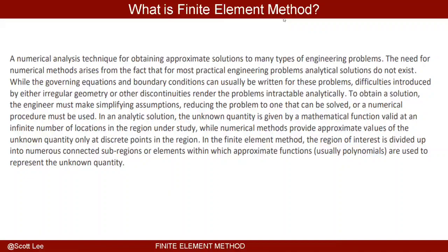Well, what you do is you simplify that domain into simple shapes like squares and triangles, and you want those triangles and squares to cover that entire domain. And if you know how to analyze the structural properties and the structural equations for that very simple shape, like a square or a triangle, then you can connect all of them together using nodes.